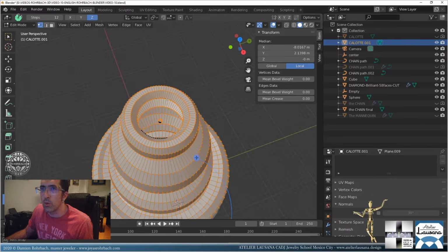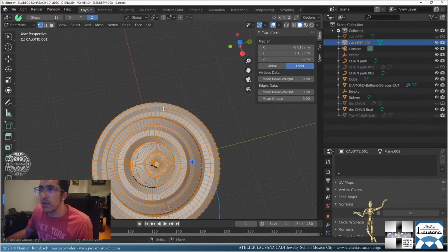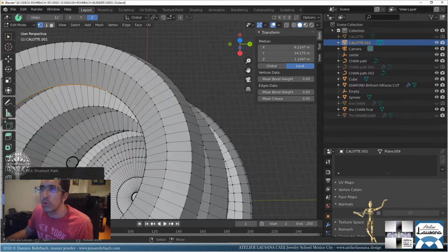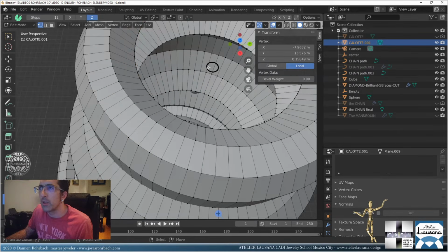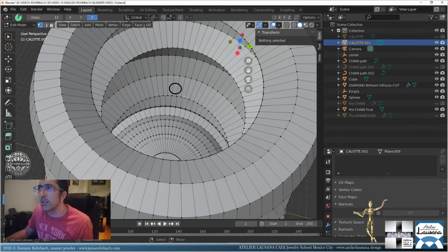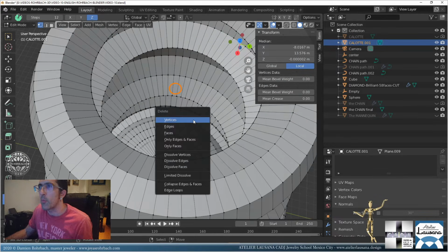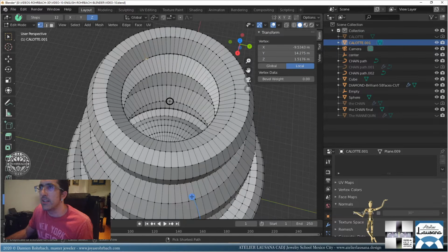So yeah, you can see that. All right, we're going to close the top view. This is funky, so let's erase this. Suppress, delete vertices. Let's take these all around here with the Control key.